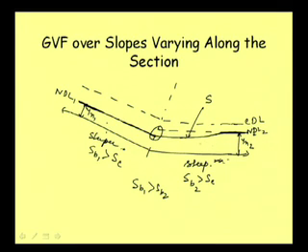So zone wise, this is zone 3, because this is less than CDL as well as less than NDL. That means it is between the bed and the lowermost line, NDL or CDL, the lowermost line. So this is in zone 3, and that's why we are finding that this is a rising profile, and this profile name is S3 profile.